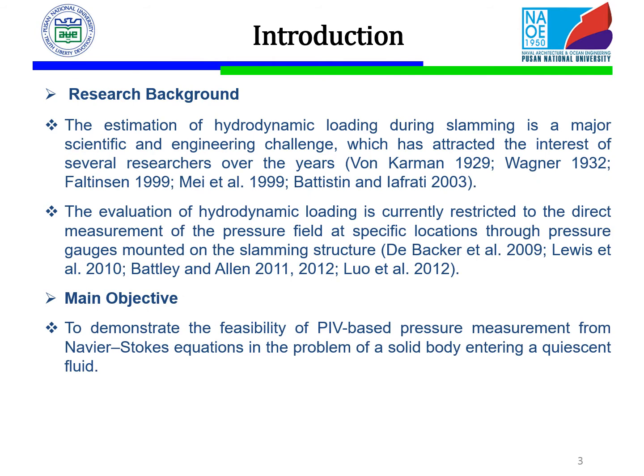The estimation of the hydrodynamic loading during slamming is a major scientific and engineering challenge, which has attracted the interest of several researchers over the years. The evaluation of the hydrodynamic loadings is currently restricted to the direct measurement of the pressure field at specific locations through pressure gauges mounted on the slamming structure.